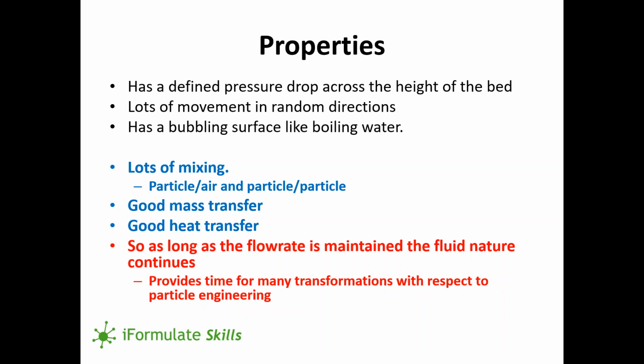One of the advantages, though, is you have lots of movement in random directions, and you have a bubbling surface, like a pan of water, and so you get lots of mixing and lots of interaction between the gas and the particles. So you have lots of particle-particle interactions and lots of gas-particle interactions, and so you can do lots of interesting chemistry onto the surface and physical transformations because of that excellent heat and mass transfer.